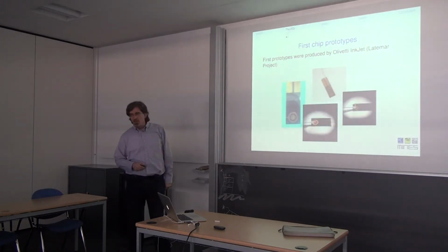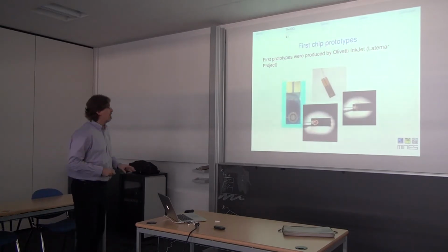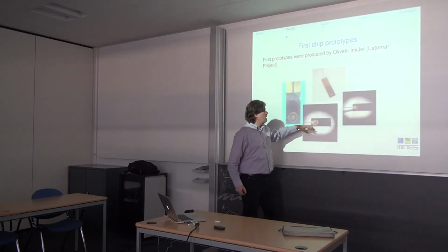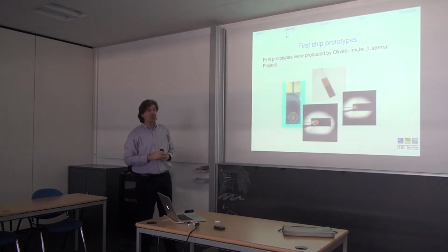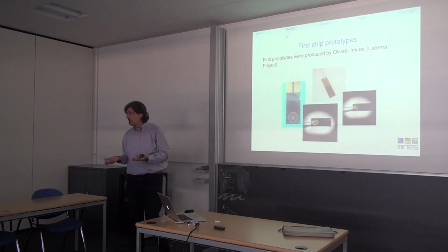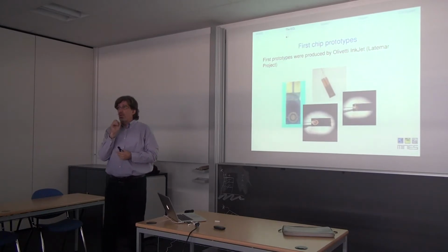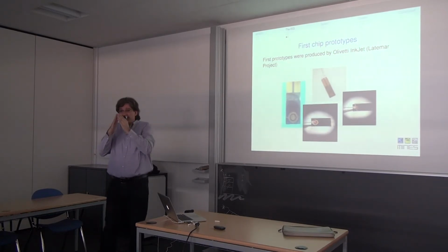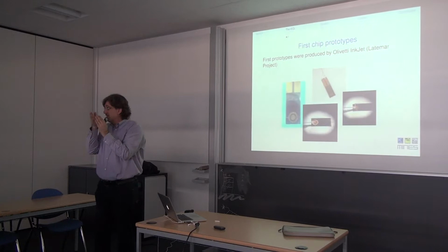What we did, I start with methods, okay? So, we built different shapes, rounded, squared, we also built stars, okay? For testing the geometry, because the geometry of the electrode is also important. And in terms of current, in the corners, in the shapes that are sharp, I have always an increase, the density of the current is higher.